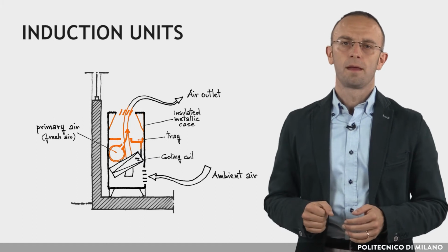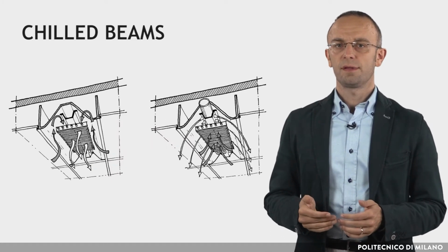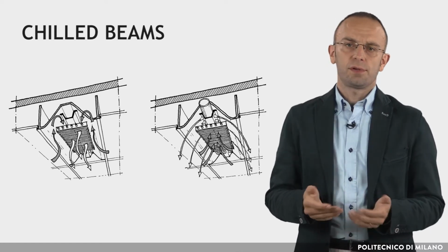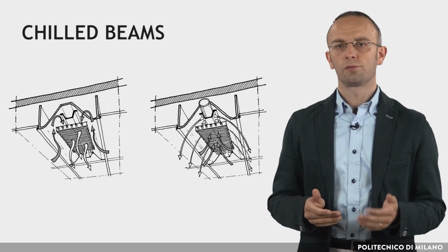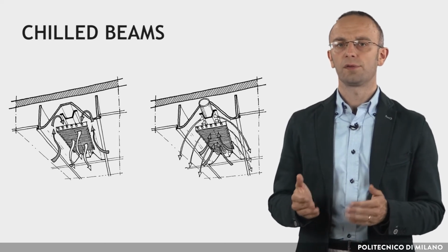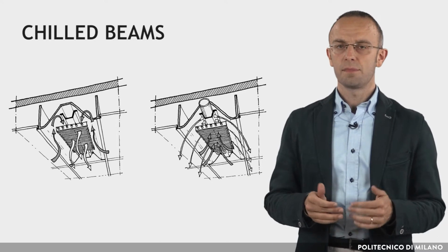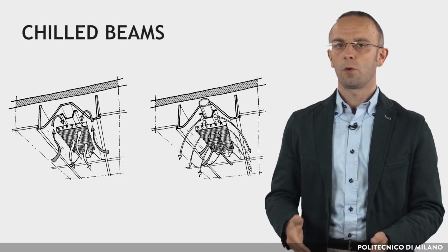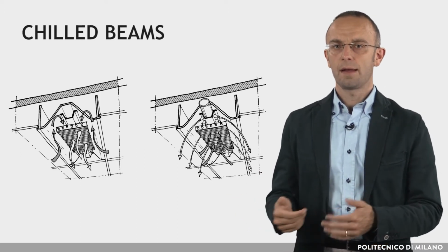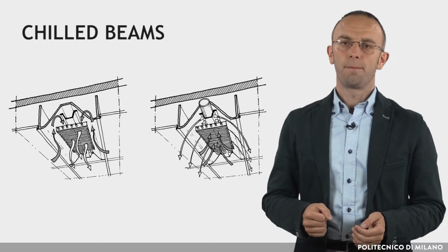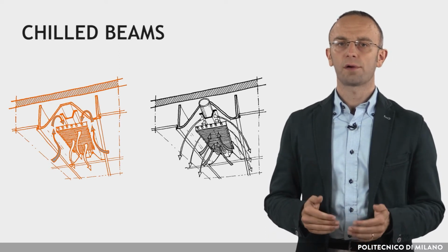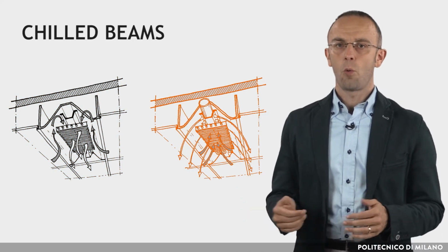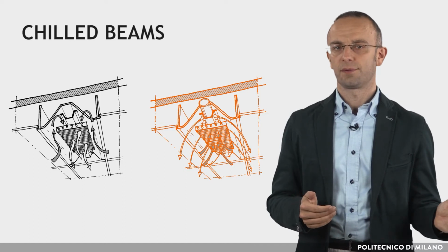Similarly, chilled beams are a type of terminal unit where water pipes are passed through a beam, which is a heat exchanger, suspended close to the ceiling or integrated into a full ceiling of a room. As the beam chills the air around it, the air becomes denser and falls to the floor, causing a constant convection flow and cooling the room. In passive systems, chilled beams can work simply by convection, or in active systems as induction units, where they are coupled with a ventilation system.